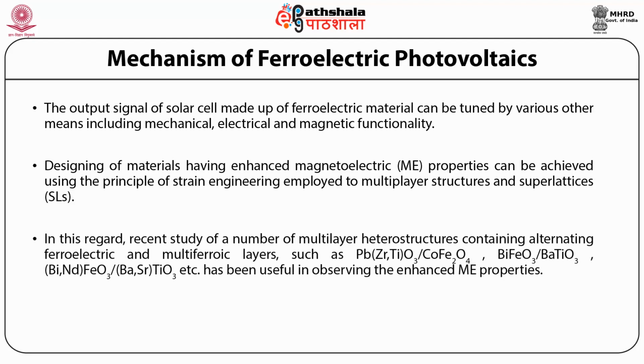In this regard, recent study of a number of multilayer heterostructures containing alternating ferroelectric and multiferroic layers, such as lead zirconium titanate and cobalt ferrite, barium titanate and bismuth ferrite, bismuth niobium ferrite and barium strontium titanate, etc., has been useful in observing the enhanced magnetoelectric properties.